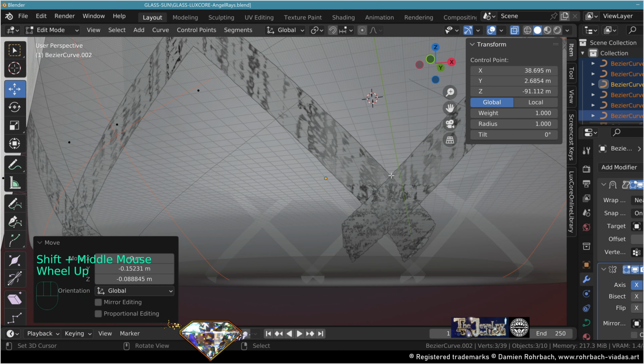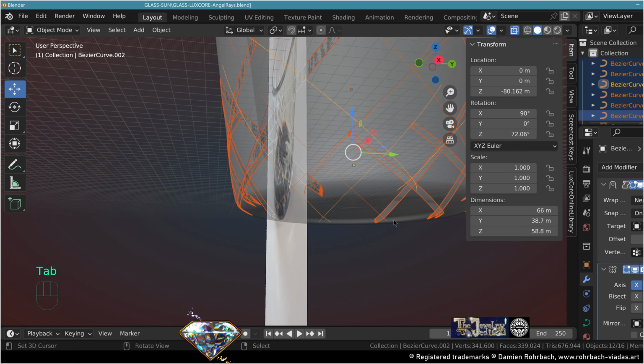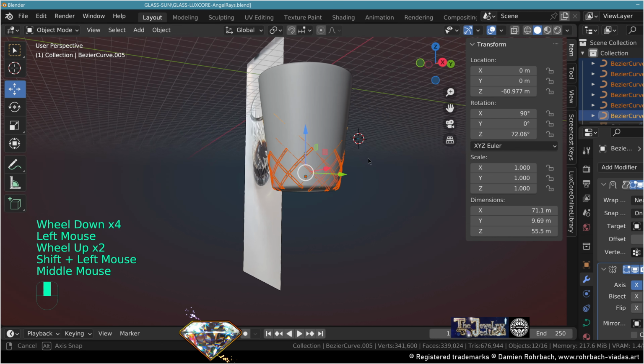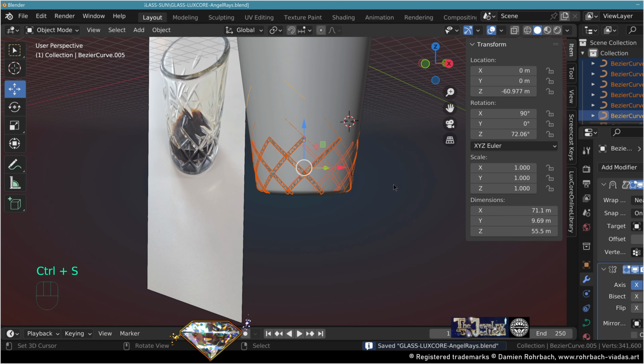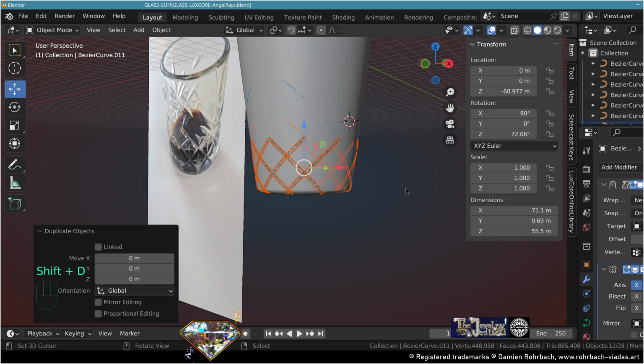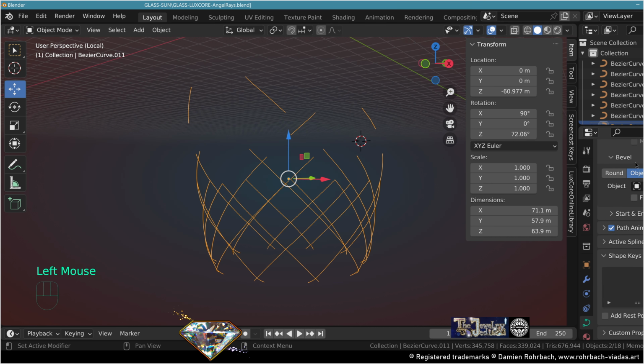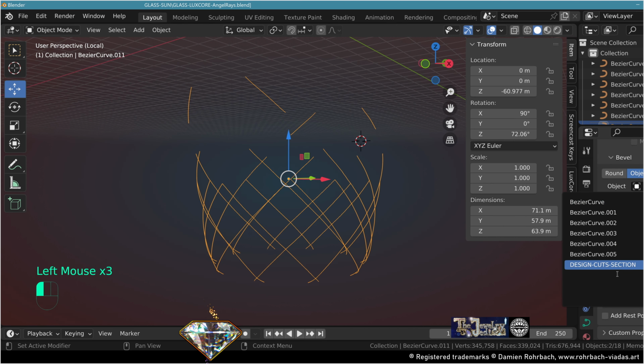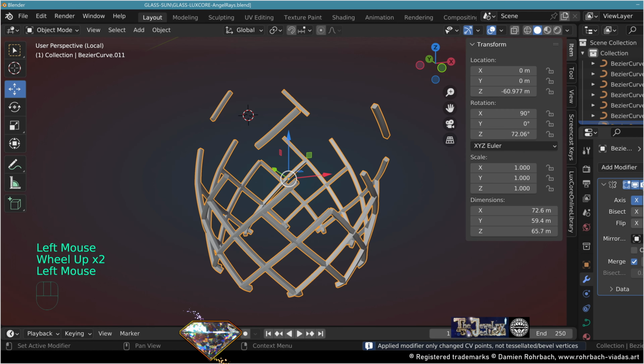They must cross the middle. We need to make the cut right there at the middle. So long enough. So again, I have all this selected. Let's make a copy. Let's join them. Let's reinstate the bevel, fill the caps. Here we are. Apply the shrink wrap.